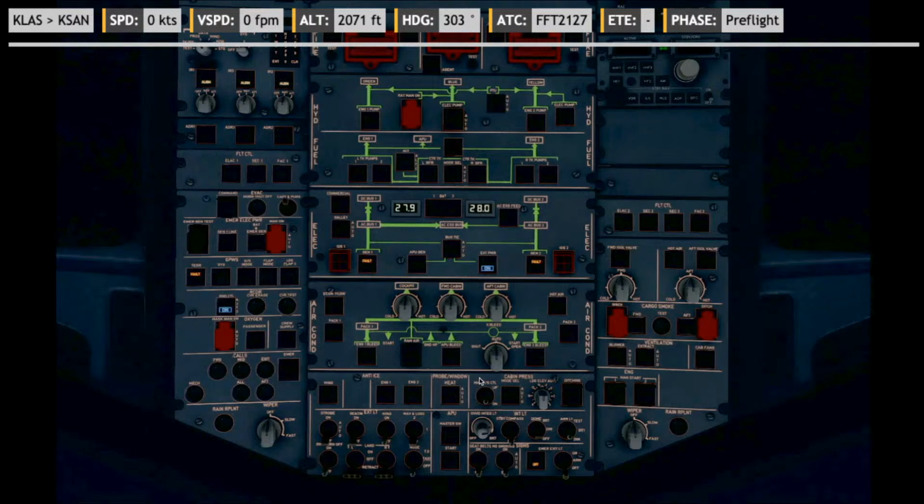Passenger and air conditioning. We are carrying 217 passengers, so that's more than the maximum for econ flow, so we'll leave it on. Engine bleeds are all normal. This is all normal, and everything is automatic. Anti-ice will not be required. Probe heat is auto. Cabin pressure is all selected. We will go strobes to auto. Beacon light can stay off. Navs to 1. These can stay off.